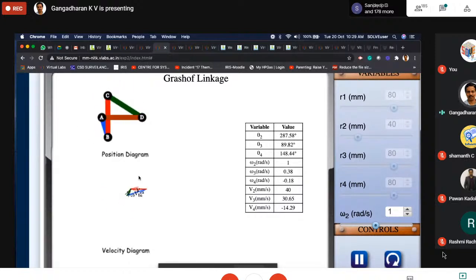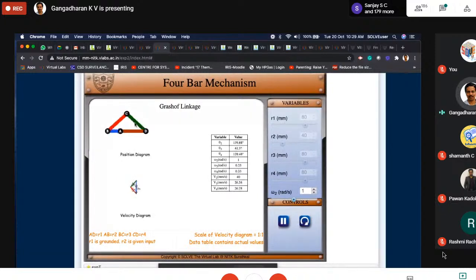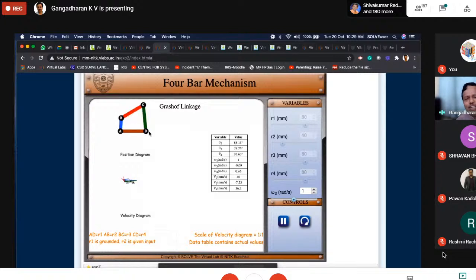So from here, now I am interested to find out how much force I need, how much torque I need to give. I want to find out what is the mass, then what velocity it has, then I need to look at what acceleration it will have. So displacement, first derivative velocity, then the next derivative acceleration. When I have acceleration attained by a mass, I get the dynamic force or an inertia force. From that I can identify what kind of torque I need to give to move it.